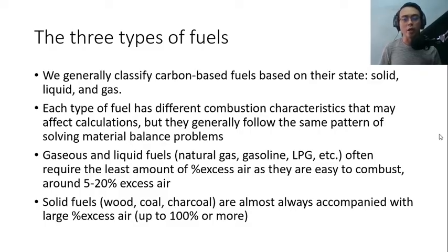Now, if you're supplying a very big amount of percent excess air, you are diluting the heat because you are introducing more air. So therefore, you are reaching lower and lower temperatures in your products or in your flue gas. So that is just one thing to ponder. Of course, we will not be discussing energy balances here. Energy balances will be discussed in your thermodynamics course, but that's just something to think about regarding percent excess air.